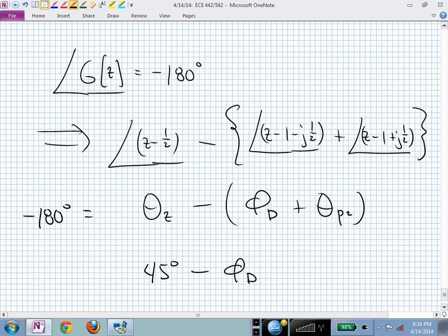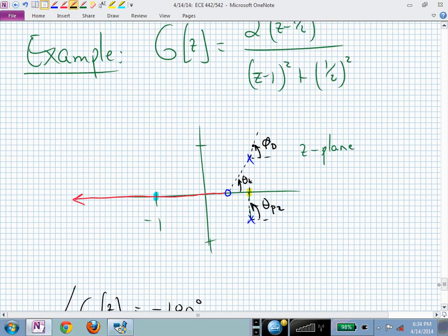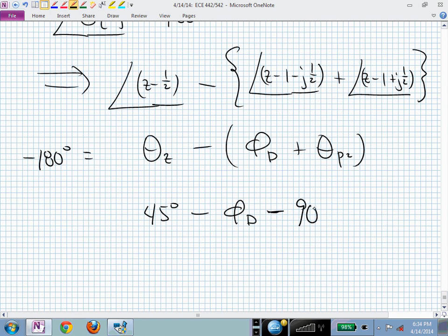That's some angle from the horizontal real line associated with that pole in the first quadrant, that complex pole. And what was theta sub p sub 2? And I'm subtracting that. I go from this pole downstairs and look straight up, which is an angle of 90 degrees. If they're on the root locus, those angles have to algebraically sum to minus 180.